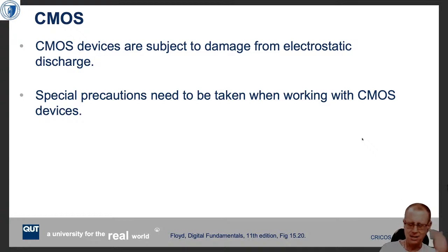Again, harking back to my internships, I used to work for a computer manufacturer in Australia, and I worked in the warranty section, the returns section, and the returns people knew that the manufacturing side, the people who made the new systems, did not understand static protections. And the returns people had anti-static mats, we had clips that we could discharge on.